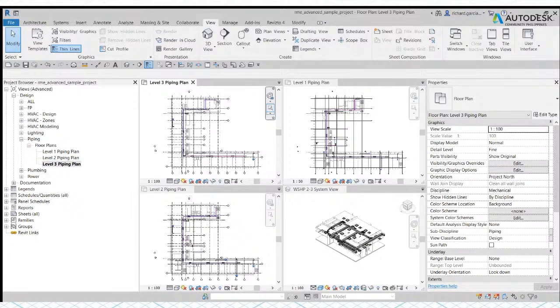There is a shortcut for that. The shortcut for zoom all to fit, take note of this, is ZA. Okay? ZA. So that's the shortcut for zoom all to fit. Okay, but then again, if you have time, you can just explore your navigation bar.